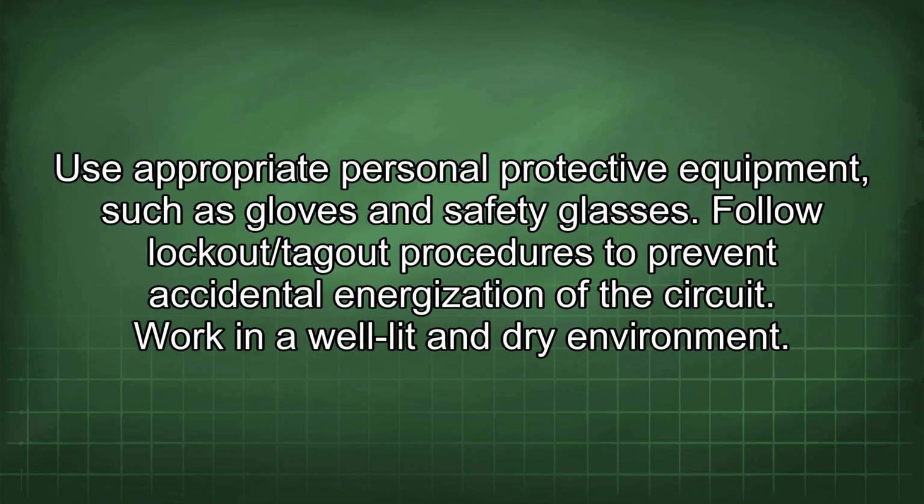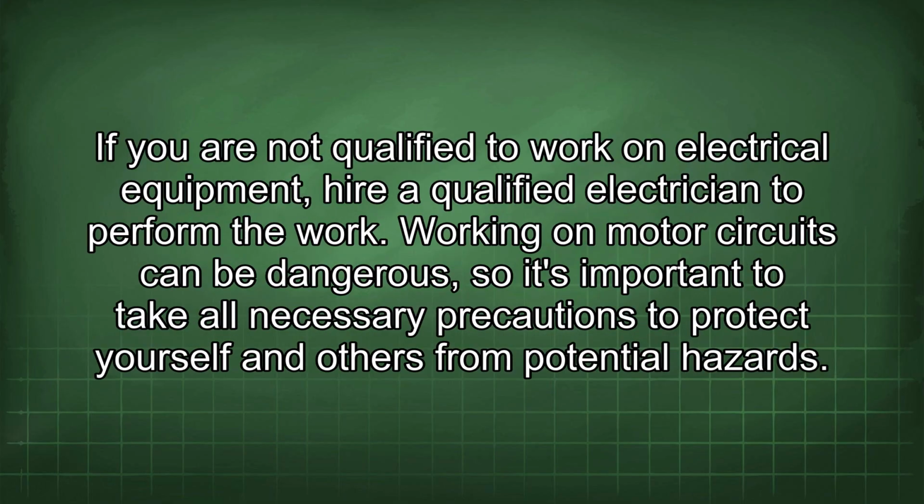Use appropriate personal protective equipment, such as gloves and safety glasses. Follow lockout/tagout procedures to prevent accidental energization of the circuit. Work in a well-lit and dry environment. If you are not qualified to work on electrical equipment, hire a qualified electrician to perform the work. Working on motor circuits can be dangerous, so it's important to take all necessary precautions to protect yourself and others